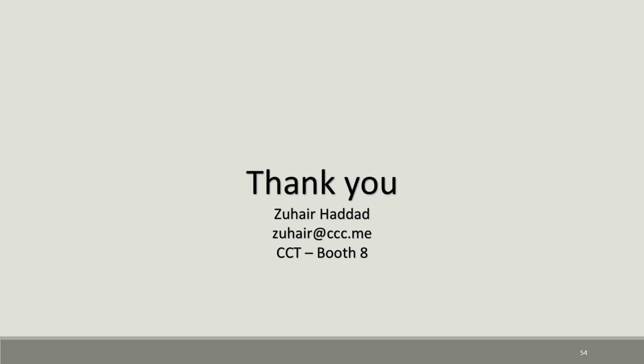before something else. So the Fragnet is how we define, after we take the set of activities we have in Primavera, which is the broad Fragnet, then we detail it using lean techniques on site, process map and all these things, to come up with the real sequence of how you build a room. And it doesn't have to be really sequential. It can be a small CPM, like a 30 activity CPM, so that when you finish one operation, you want to find who can work in this room. And we're building a simulator trying to optimize this process.